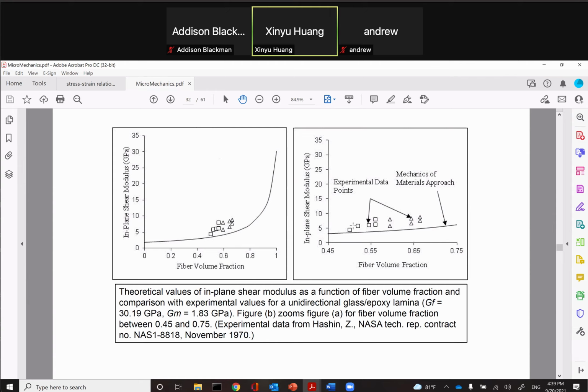Modulus, if you have numerical tools, you have good inputs, you can get within a few percent. Your prediction matches experiment beautifully, usually. For strength, it's way more difficult. Even though you know the strengths of all the constituents, you put them together and predict strength. Because they introduce a weak interface, all those things, it's very hard. If you get to like 10, 20, 30%, it's pretty good. Okay, that's an excellent job. The difficulty from predicting stiffness to predicting strength is an order of magnitude more difficult.